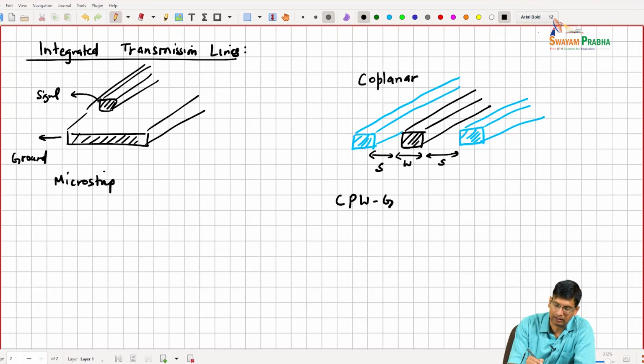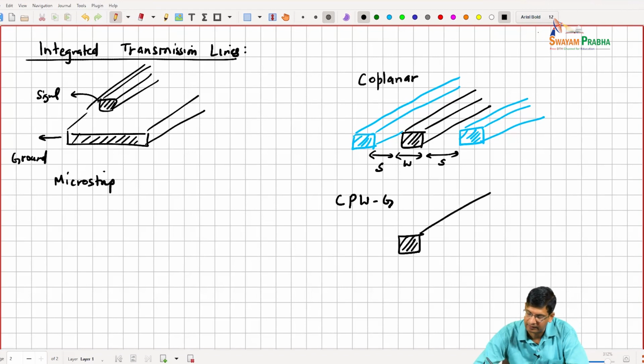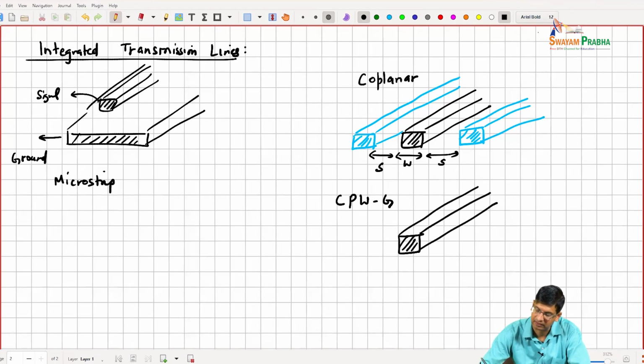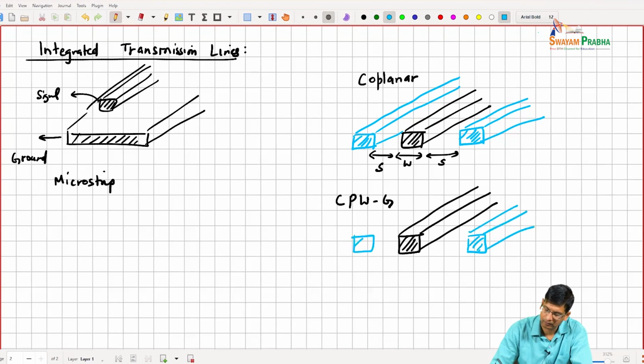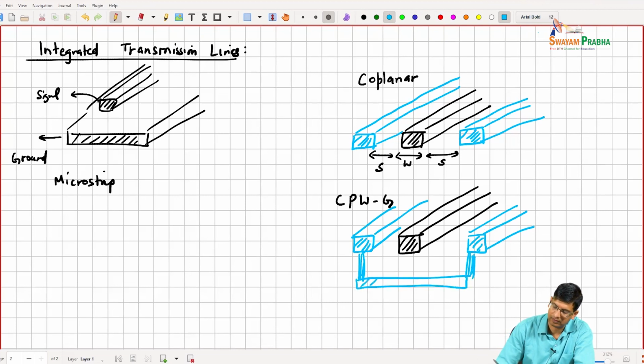So we do the exact same thing, and this is what we've been implementing, where we have the signal trace, we have the ground trace, and we add a set of vias that take you to a lower metal layer, and we also implement ground in there, right?